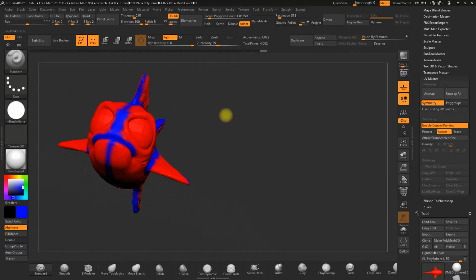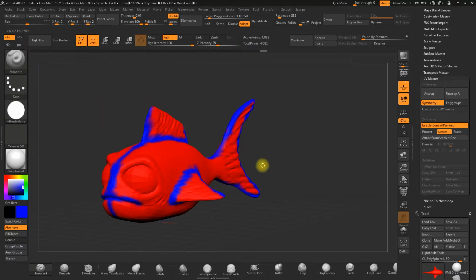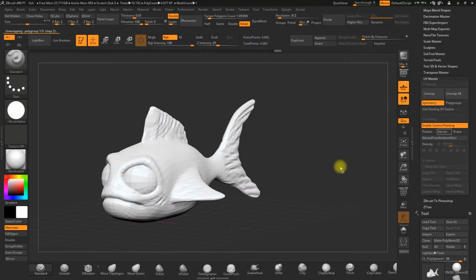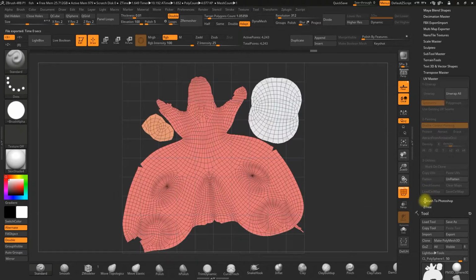Okay. All right, now that we've done all this, you'll get why we did it if you didn't know already. Let's click Unwrap, we wait, and even if nothing happens, if we click Flatten, we'll see the texture surrounding the model, flat, like in 2 dimensions. Let's click it, and as you see, we get the body of the fish. As you see, the texture is stretched flat, and we can see here the fins, for example.